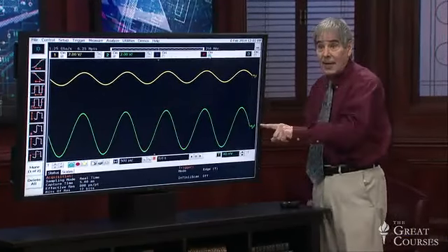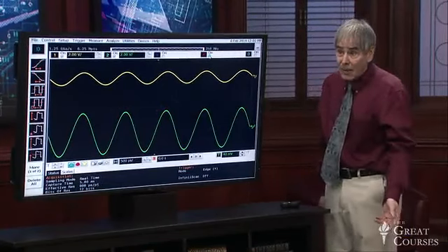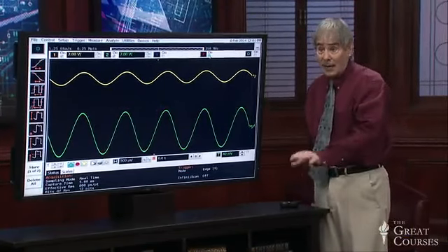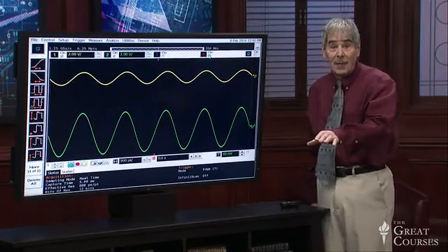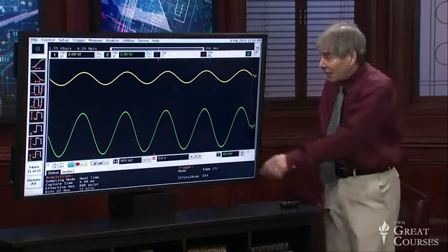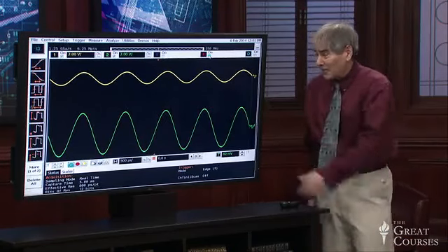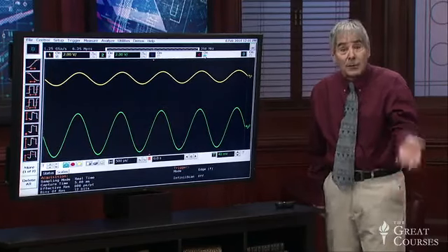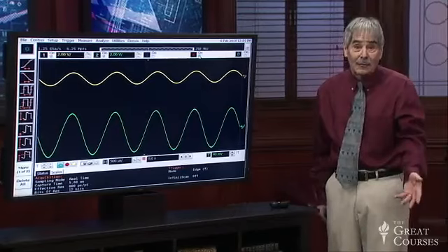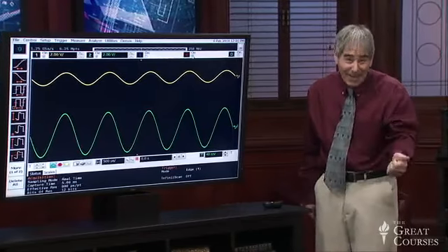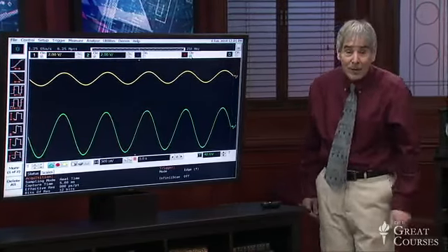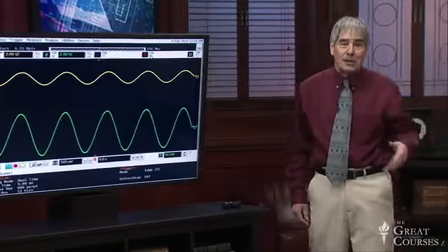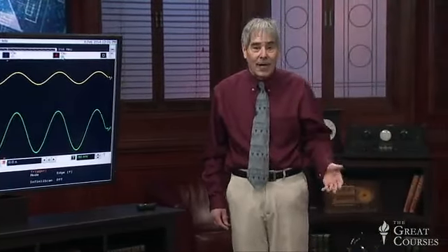There it is. Make it out of 2 inverting amplifiers, one with a gain of -3, and the other with a gain of -1. Okay, so that's what we did. Works great. We could have, by the way, had a gain of the square root of 3 in each amplifier if we had wanted, and we still would have come out with 3, but I chose to make a gain of -3 and a gain of -1. So there is a simple embellishment on our idea of inverting amplifiers.